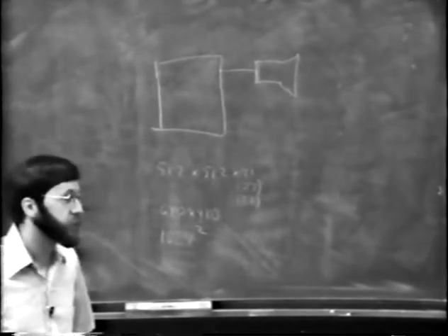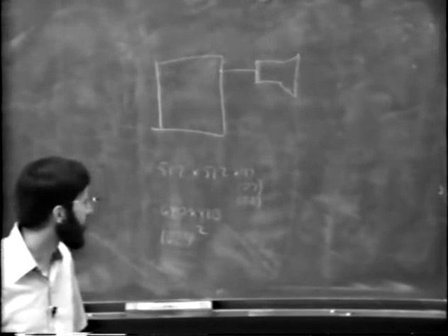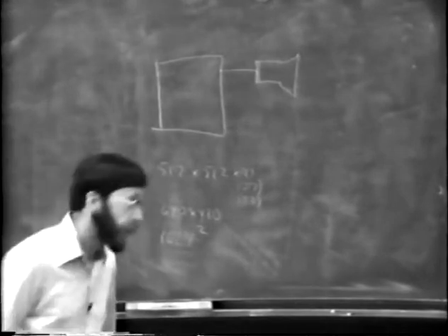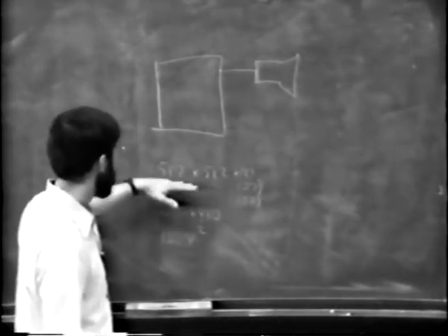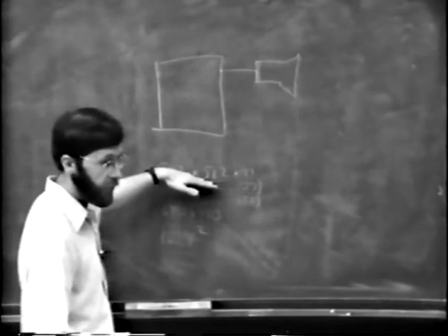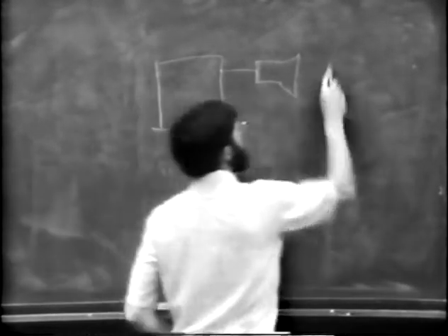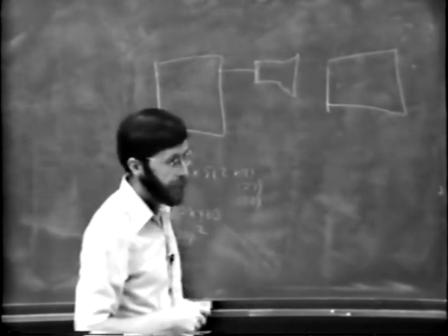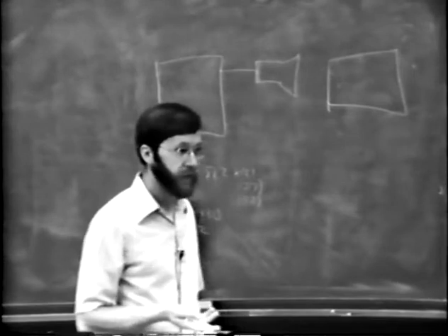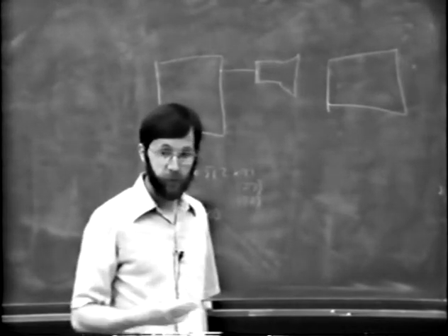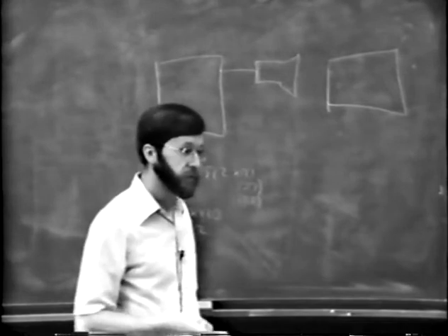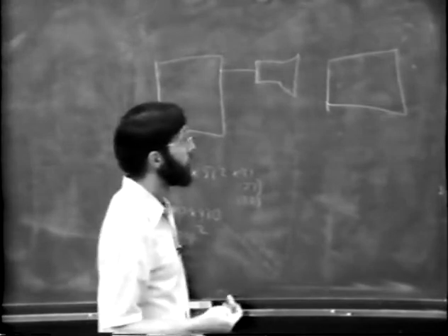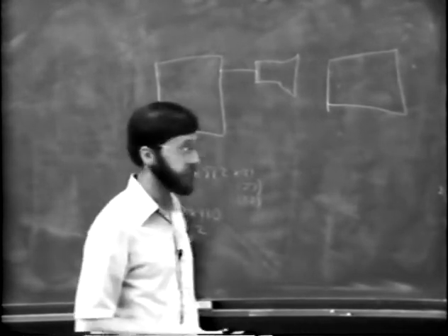Now, our first reaction to this aspect ratio was that it is a pain in the neck to have non-square pixels. Now, these things are displayed on a television monitor. Well, the television screen has an aspect ratio of 3:4. Now, if you ever get a frame buffer, you should get one where you can underscan the monitor, because most monitors come with overscan. You need one that's RGB and underscan, and those monitors are at least $3,000, I think, and a good one is more like $6,000 or $7,000.